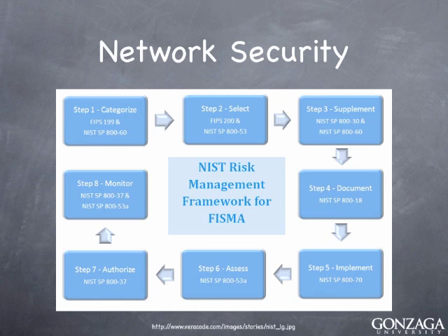The first might have been a security by obscurity approach, where networks were built highly proprietary, not a lot of interconnection. You might have control network built upon control network built upon control network, and nothing is exchanging information with one another. The circuits are all point to point. It's a very hub and spoke relationship, and it's usually using a fairly antiquated communications method. We actually have some of those systems still in place at Avista, but are migrating away from them just because of the demands of technology.